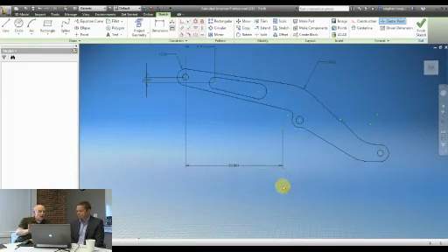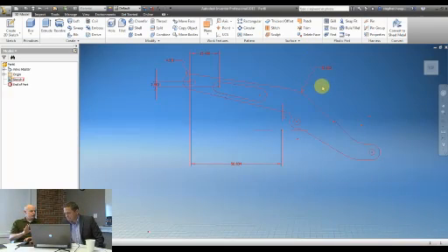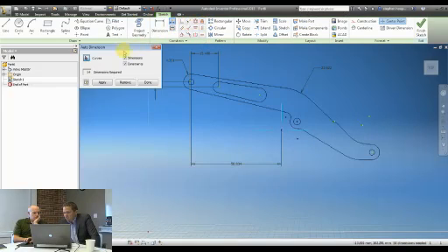So here we are. Now it automatically opens up in Inventor. I'm the AutoCAD guy. I just clicked on the reuse 2D workflow. It asked me for the drawing. I look at it, choose the pieces, and now we're in Inventor. So it's actually taken things one step further, because it's not only translated the dimensions and the drawing geometry, but I can start to add intelligence to it now.